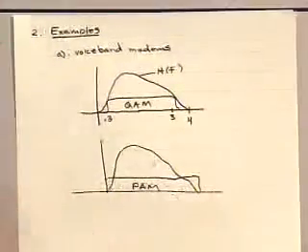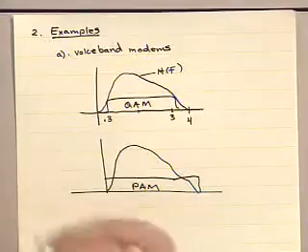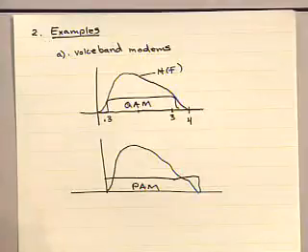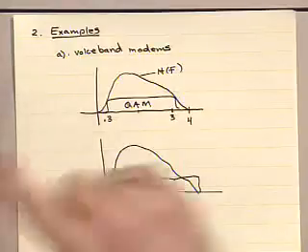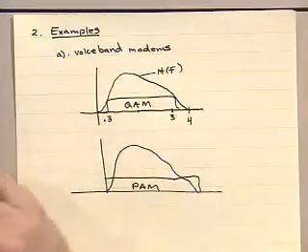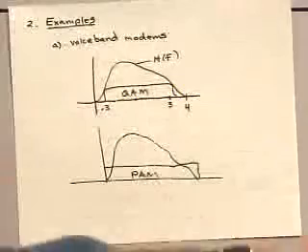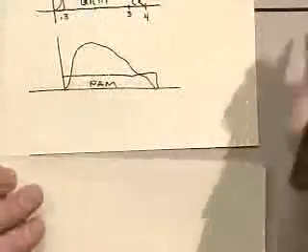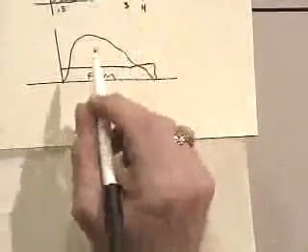Well, we're going to try to flatten the channel in the receiver. So you asked about doing it in the transmitter. We're going to try to do it in the receiver. The equivalent of the energy blowing up to infinity on the transmit side is going to turn out to be the noise being blown up on the receive side. It's called noise enhancement. We're going to learn how to best compromise between increasing the noise power and improving the transmission rate for such a system.